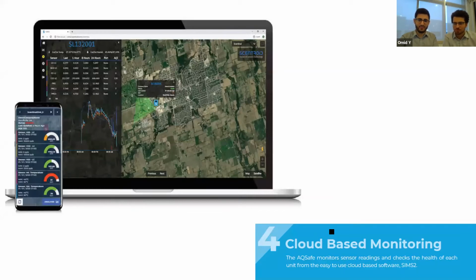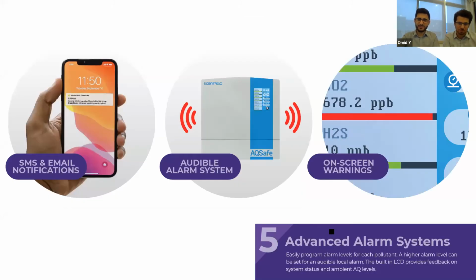We're going to go into more detail after this, but before diving deep into that, I'm just going to tell you that in terms of the alarms and notifications, there are 3 levels of notification in this product, depending on the severity or the concentration of the pollutants in the environment. First and foremost is the SMS and email notification system. You can set that up on the cloud, and whenever a threshold is reached, for example, CO2 levels reach about 800 ppm, which you can customize in the settings, you'll get an SMS and email notification that the level has been reached.